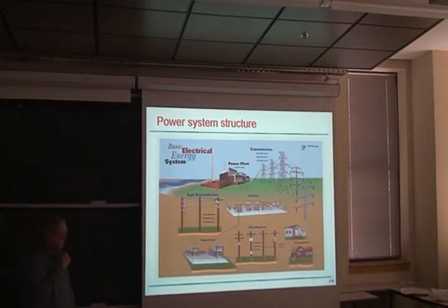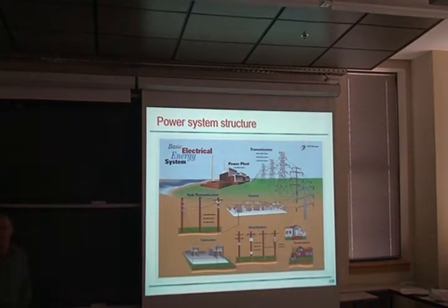And we're working with Detroit Edison and addressing some of those issues, but the point is that wind is going in at 40 kV because of economic reasons. Here, it's going in at 500 kV in Portland, in Oregon, near Portland, again, for the economic reasons in that case. So there's no one notion of interconnection that fits all.